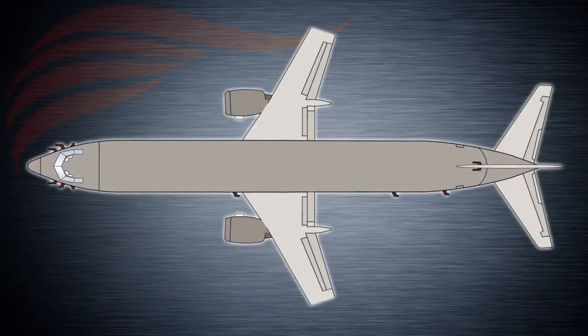The Next Generation 737 has ice protection systems for the engine inlet cowls, the wing leading edges, the air data probes, and the flight deck windows. Water and waste system lines and drains are also heated to prevent ice expansion damage and blockage. Drain masts on the underside of the fuselage are heated to prevent ice formations from breaking off and damaging the aircraft structure. The aircraft also has windshield wipers and a rain repellent coating on the flight deck number 1 windows for rain removal.